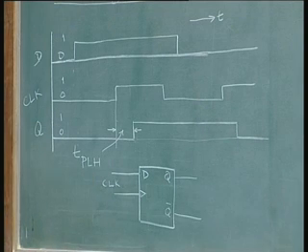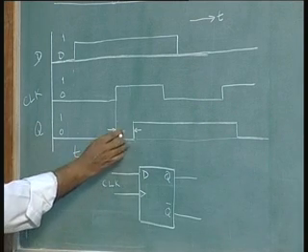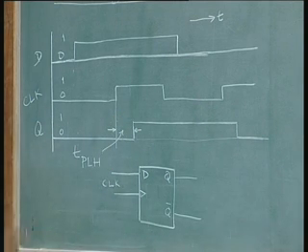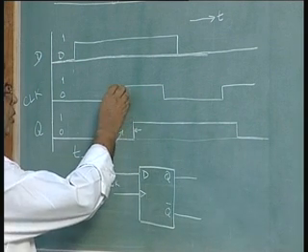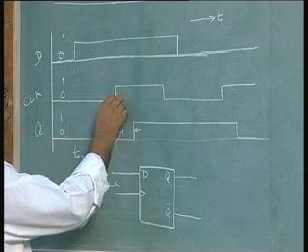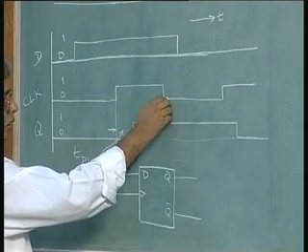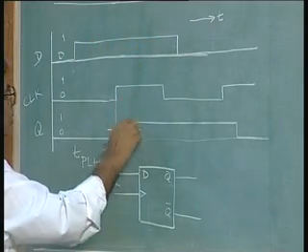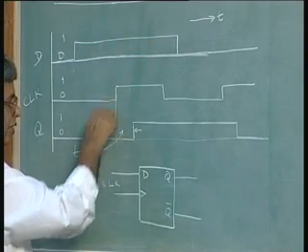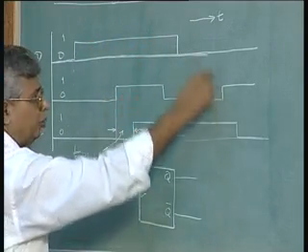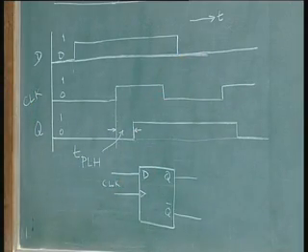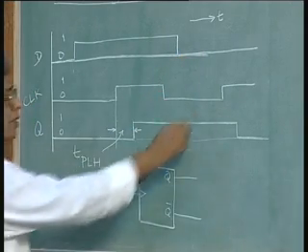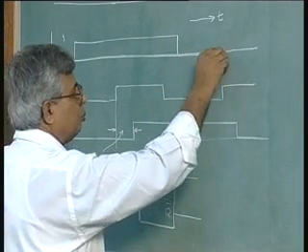If the output has to change from low to high, the amount of time required for that propagation is called propagation delay, TPLH. Likewise, when the clock is made 0, the output does not change because output continues to be D, and the next time the positive edge occurs, only the input will be looked at, and when that happens we see that the input is 0.